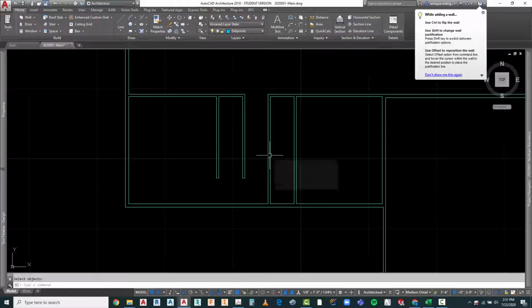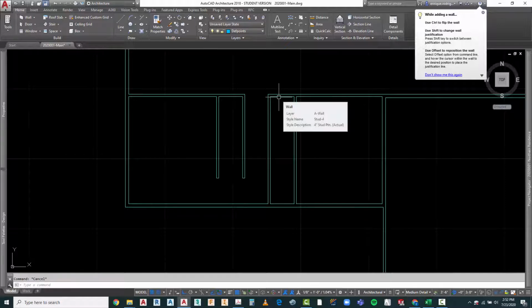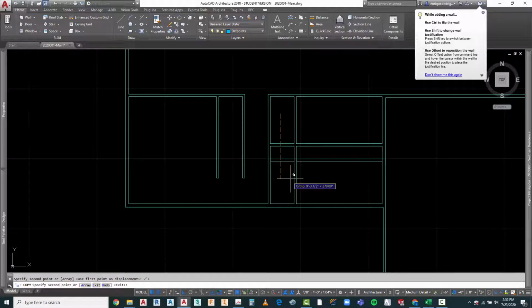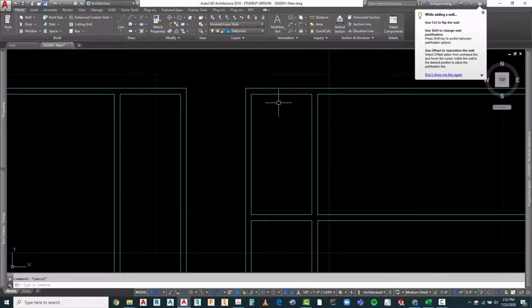Now let's take a look at the bathrooms, and what we have is a 3'6" and a 3'7", which gives me 7'1", which is going to be to the outside wall in here. So I can copy this 7'1". But I need to take a close look at what we've got going on in here, because if I take a look at my markups, this section of the wall right here, because there's a toilet there, is going to be 6 inches deep instead of 4.